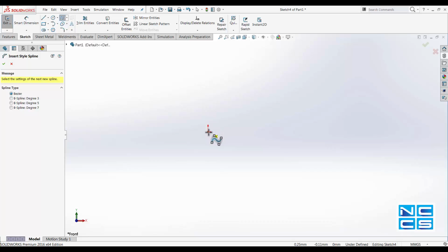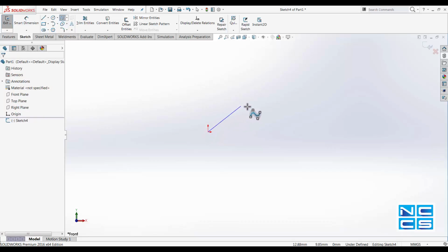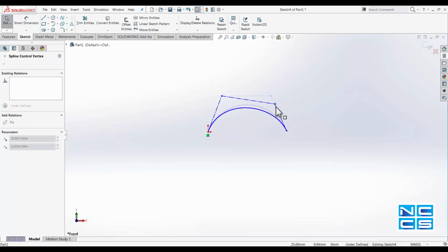You can create a curve simply by drawing onto your first control point, second control point, and third and last control point. This will create one smooth span, and you can use the control points to modify and refine your curve.